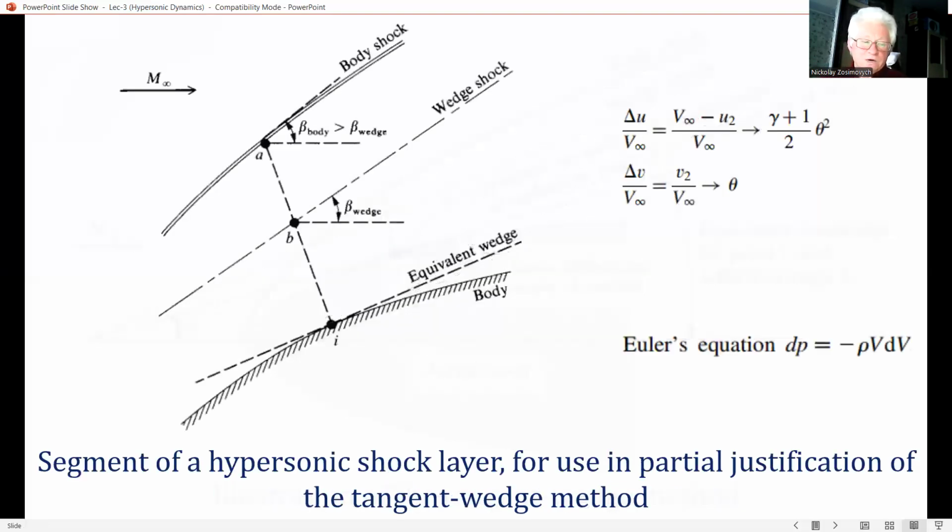And the region around this line is isolated and magnified, and you can see in this diagram, I magnified it. And now consider the following fact. In hypersonic flow, for an oblique shock wave on a slanted body, the y component of the flow velocity v is changed much more strongly than the x component u.